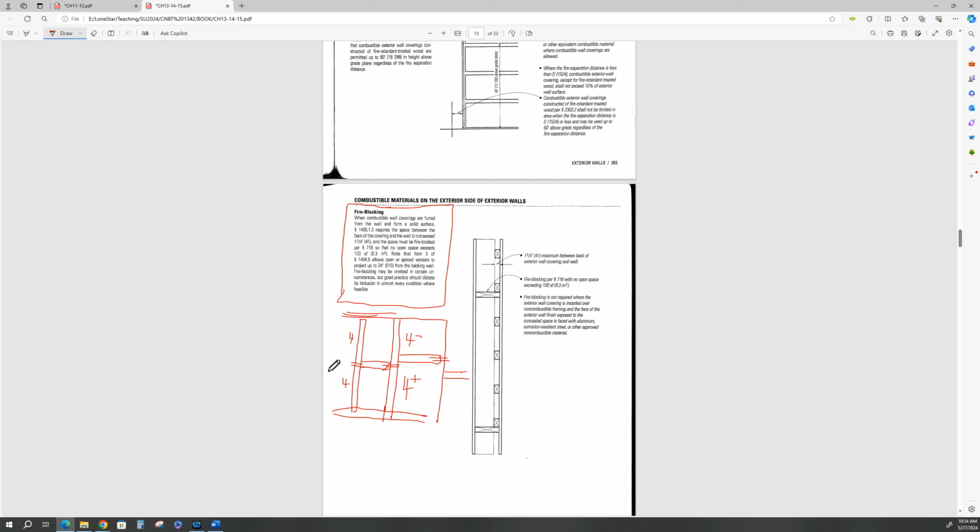But because we're worried about fire, what does this do? You get a fire down here. Maybe the fire load is down here. All right, let's put the little fire gizmo. Fire, oh no, it's burning. Okay, and we have a penetration here, and it finally comes. It keeps the smoke in the chimney and the hot gases from cycling up through this narrow wall cavity, because it blocks it.